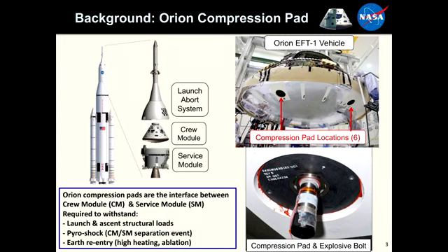And so what we actually have here is a heat shield, which you normally want to be a low density material. You don't want to add much weight for launching into space. You have a heat shield that's low density, but these regions where it's structurally connected to the rest of the rocket, you need to have a very robust structural ablative material system. And that's where 3D MAT came in, because we couldn't find a material to meet the requirements of that particular location.